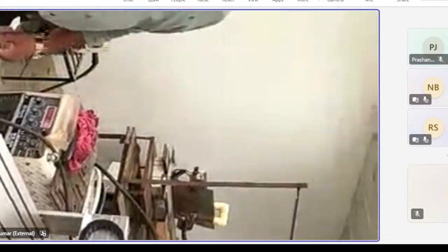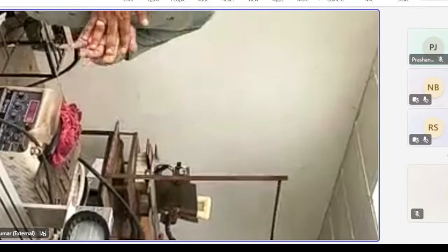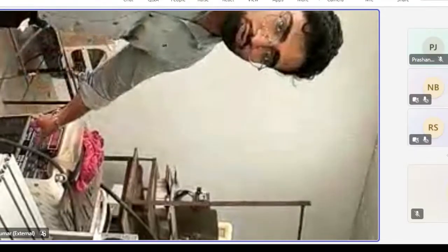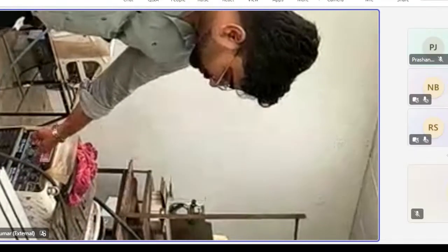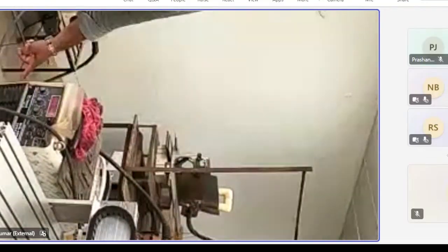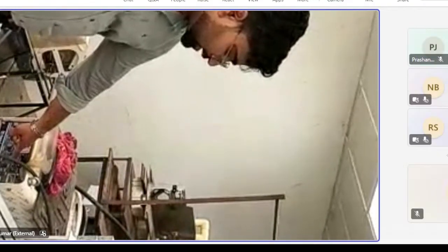The most important thing to keep in consideration during this machine, otherwise when you experiment there are a lot of challenges that we generally face, is that the mode should be in GMAW mode. Another part is that you are using solid wire for depositing the material, so you should make sure before operating this machine that your mode is set to solid. There is another knob given, 0.8, 1.0, 1.2.